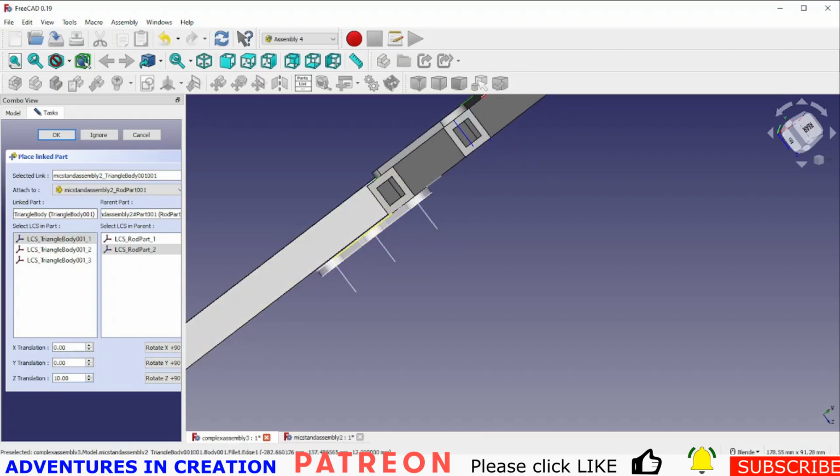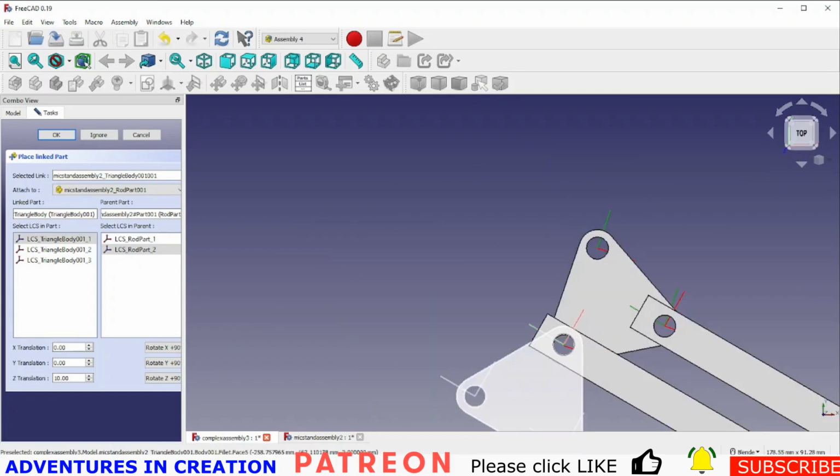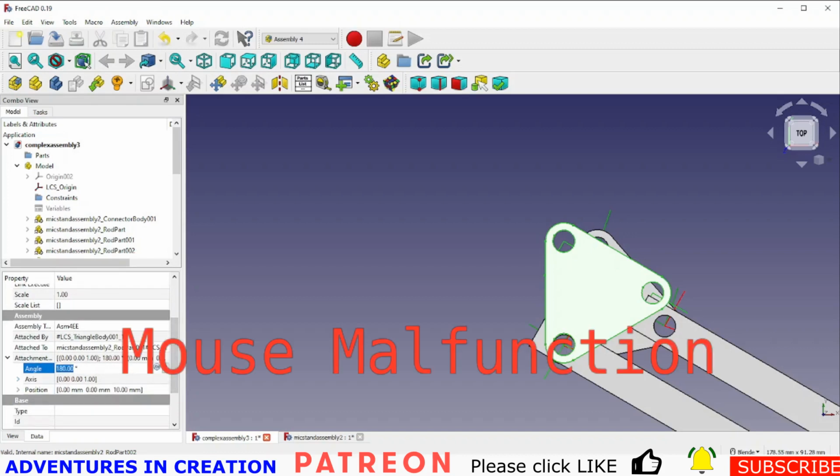So remember, this thickness is 2. So when it was in line with there, we only had to move it 10. And then what we're going to do is just flip it around. This one is actually an easier shape. So I'm going to rotate it once, twice, say OK. And then I'm going to go down here to my fine tuning.